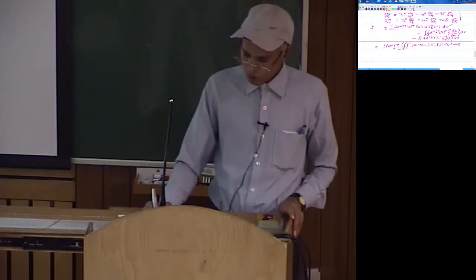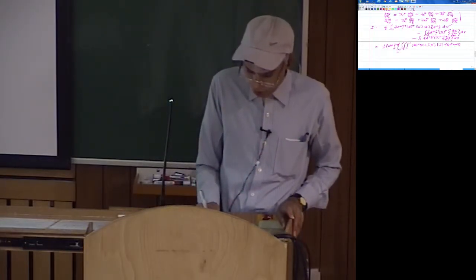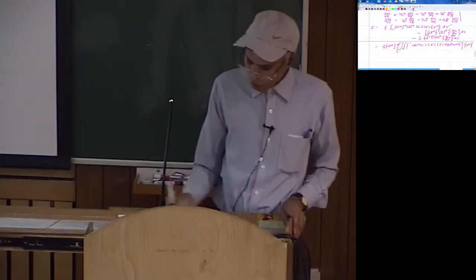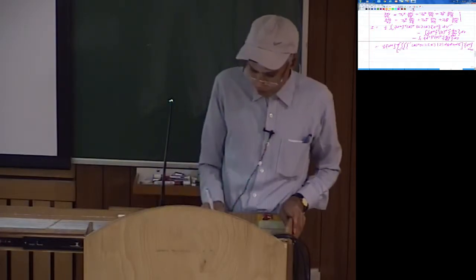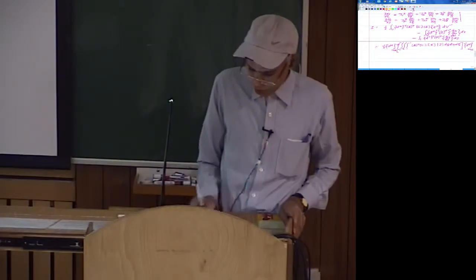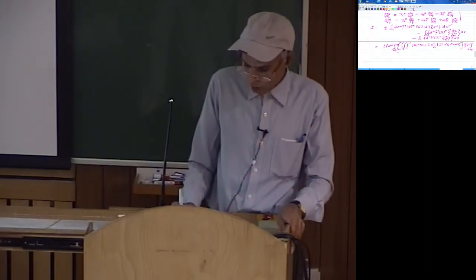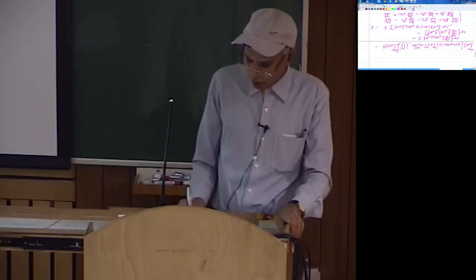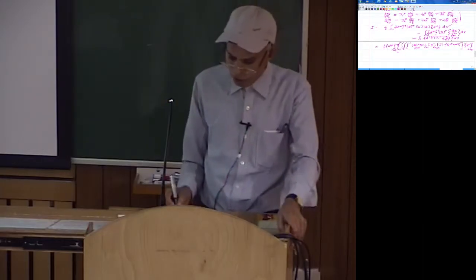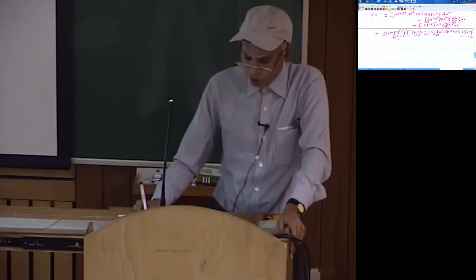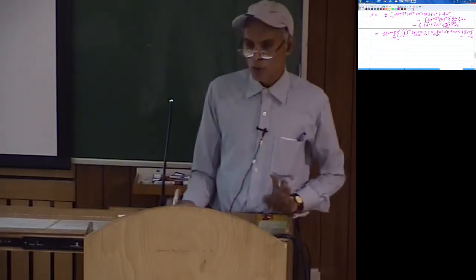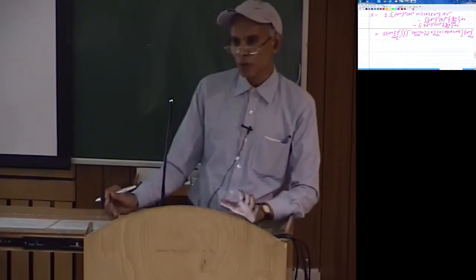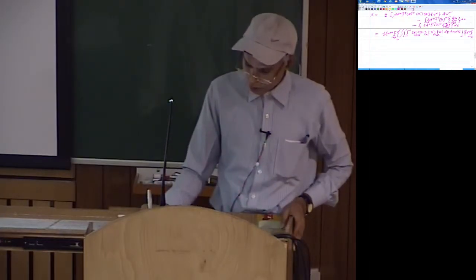So this is the first term, and finally this is what is your stiffness matrix, and this side you will have dE. If you look at dE, it is 24 by 1, and we have seen its transpose is 1 by 24. Here B is 6 by 24, this is 6 by 6, and B transpose is 24 by 6. So finally the matrix in between is actually going to be a 24 by 24 matrix. So now the element level stiffness matrix for an 8 noded brick element is 24 by 24. That is what you get, and the vector of elemental degrees of freedom we already talked about.